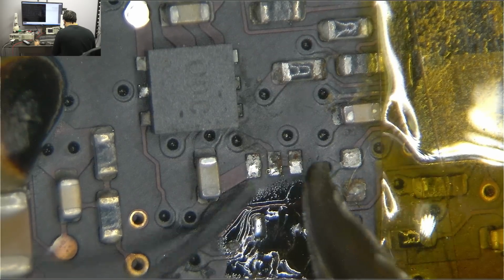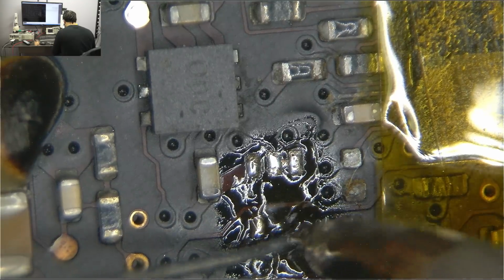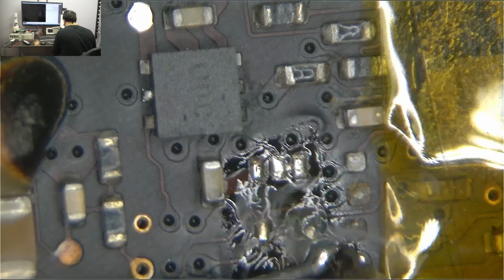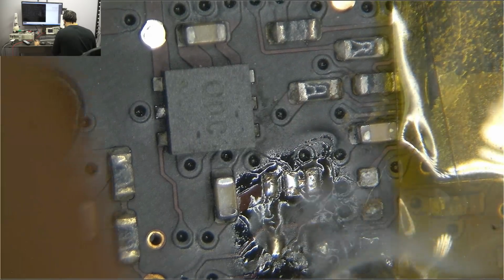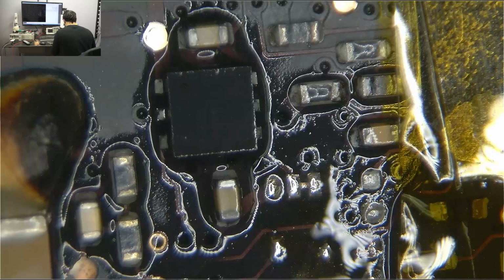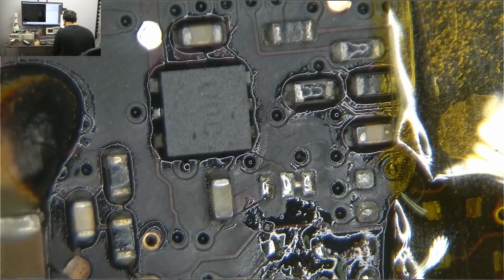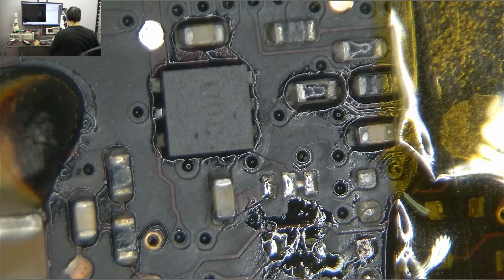So what I'm doing right now is I'm just going over these solder pads over here with the iron, and there's one pad in particular that's interesting to me because it's kind of destroyed. I'm probably going to be running a wire to it. So let's just see what this looks like after a little bit of cleaning. Yeah, this looks like crap. You can tell that there's a pad right here that's scratched away, and this actually got stuck on my tweezers. So let's see what we can do about that pad.